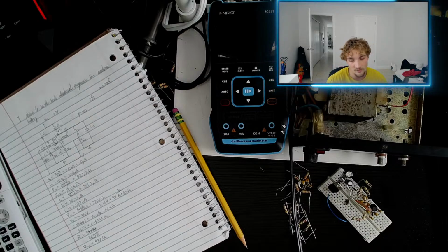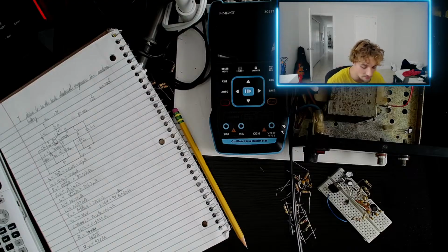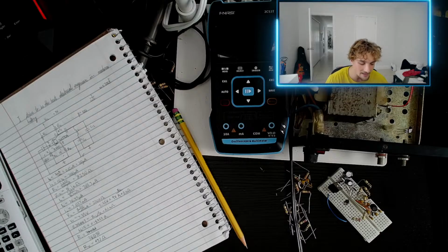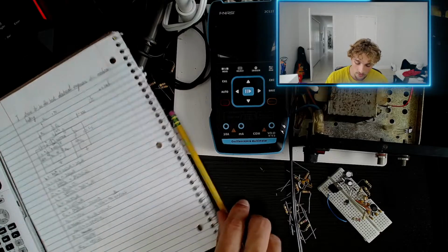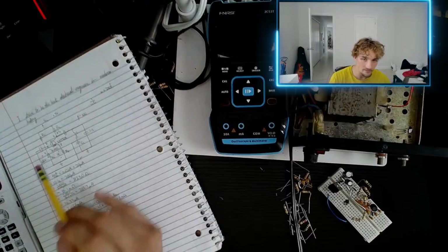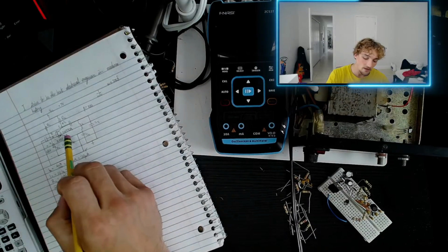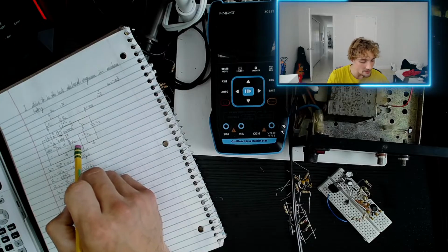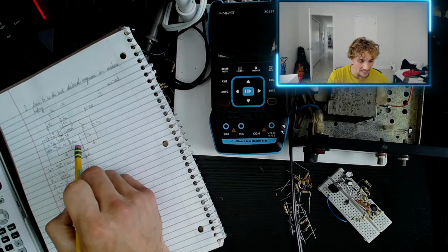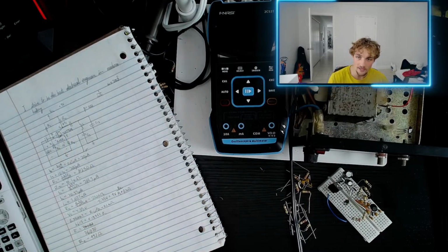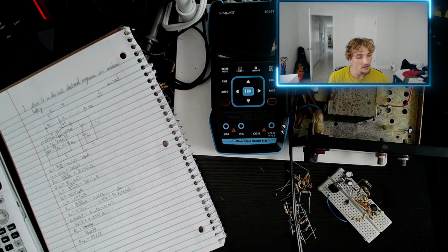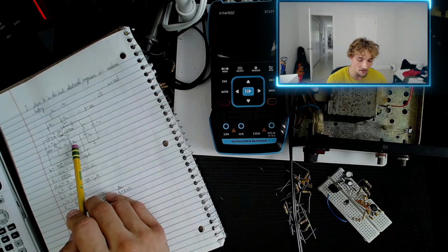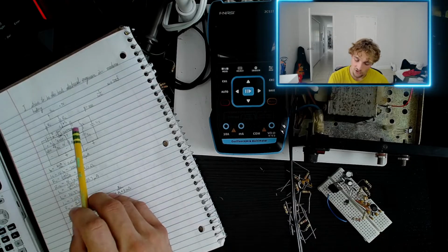When we do the small signal analysis, we're going to have to consider the value of our emitter resistor. A way around it is that, in parallel to the emitter resistor, we can add another resistor and a capacitor, right? At low frequencies, the capacitor will act as an open circuit. But at high frequencies, at our operating frequency, the capacitor will act as a short, right?